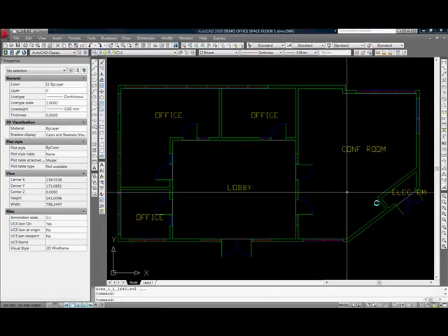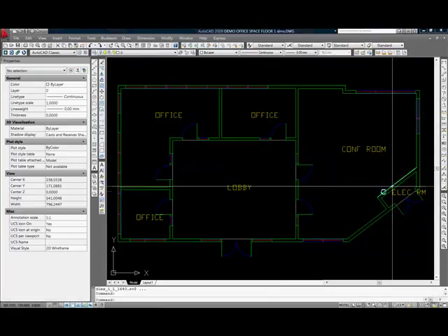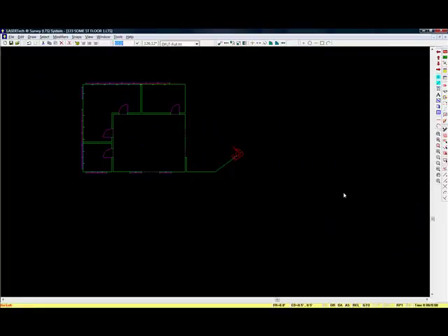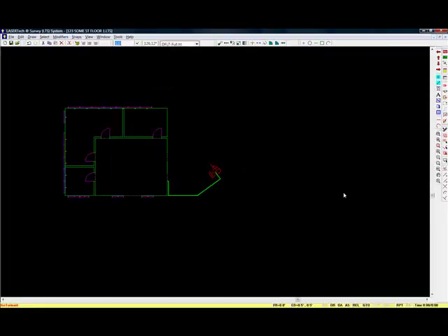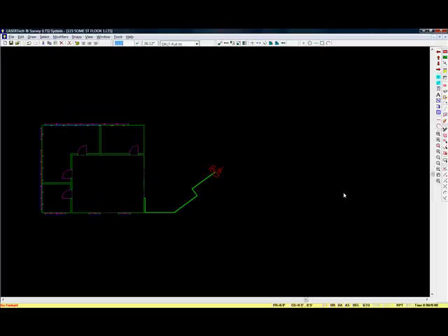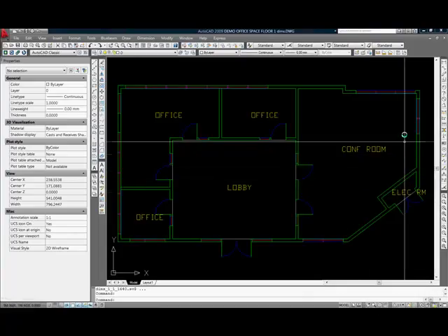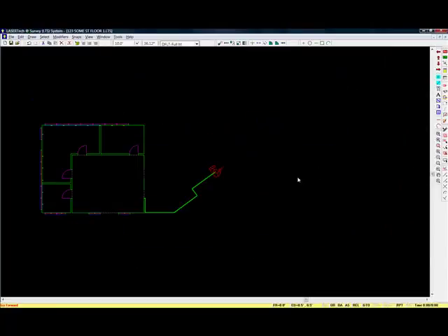And now you can see in the drawing everything here is square to that angle, so we would just turn and measure, and it's 3 feet, and then we turn again and we find it's 10 feet. And now you can see back in AutoCAD we want to get back onto our grid, and so we have a way to do that. We go into what's called absolute mode, and now we can just force it to go up on the screen,